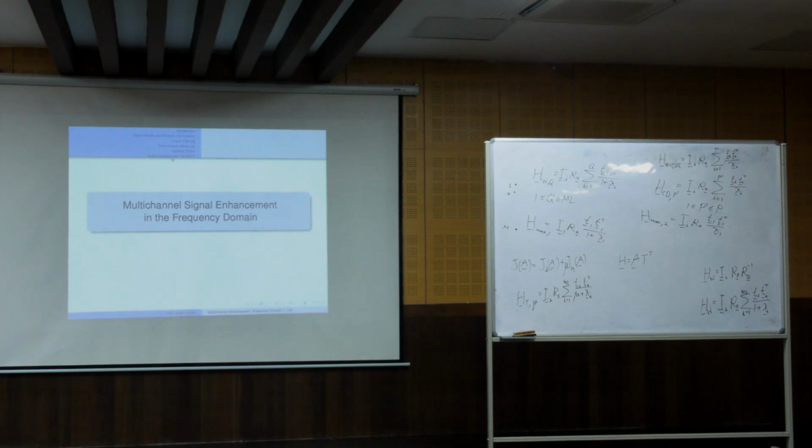Now that you understand the single channel in the time domain, you saw that when we move to multi-channel in the time domain, it's an extension of the problem formulation, the derivation, and so on. And we did some extension that was really nice. We found that the filtering matrices take into account the temporal correlation and also the spatial correlation in the vectors.